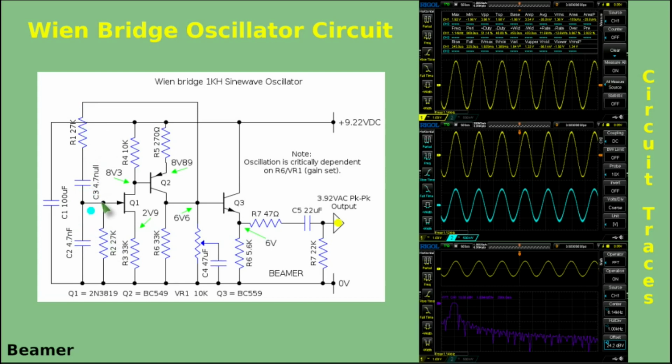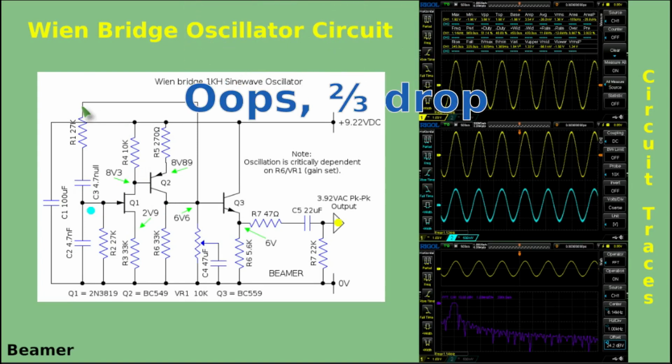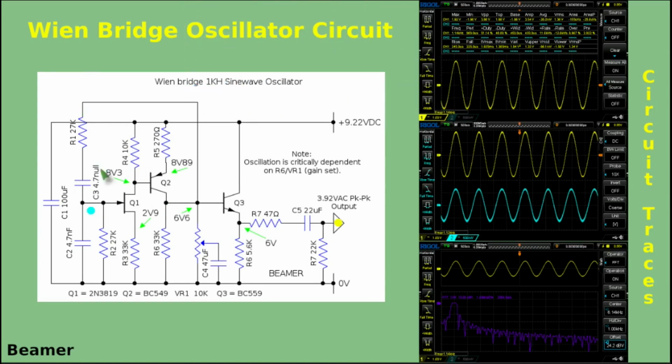It is of a zero phase, and that is important because, as we just said, we've got 180 degrees across here and we've got an additional 180 degrees across here. Well, the sum of those two is 360 degrees or 0 degrees. Now, if there is a third drop between the input of this Wien Bridge and its output, to make this circuit oscillate, we have the primary ingredients of a 360 degree phase shift.